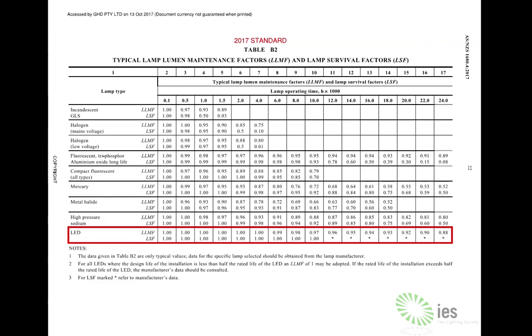So, when using occupancy sensors, does switching cycles on an LED impact it adversely? It won't affect the LED chip. It may affect the driver depending on the quality of the driver. So ultimately the LED chip prefers to be cold, and that's all the LED typically cares about. But the driver will notice transient spikes, will notice harmonics, will notice your power factor, all that electrical side of things, including your switching, that's affecting your driver. Once it's passed through a driver and all it's getting is a constant current or a constant voltage, the LED doesn't care as long as it's cold.